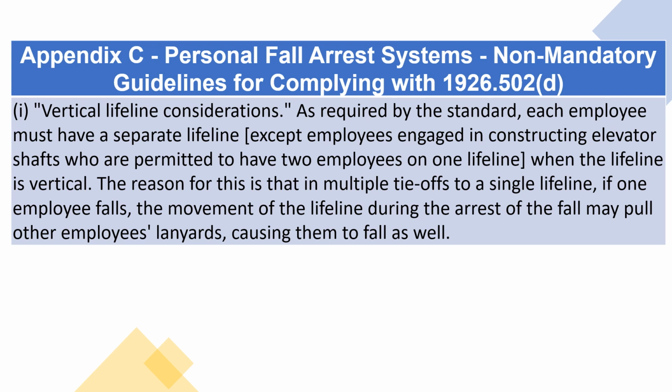Vertical lifeline considerations. As required by the standard, each employee must have a separate lifeline, except employees engaged in constructing elevator shafts who are permitted to have 2 employees on one lifeline when the lifeline is vertical. The reason for this is that in multiple tie-offs to a single lifeline, if one employee falls, the movement of the lifeline during the arrest of the fall may pull other employees' lanyards, causing them to fall as well.